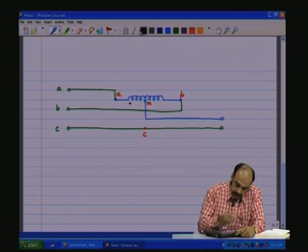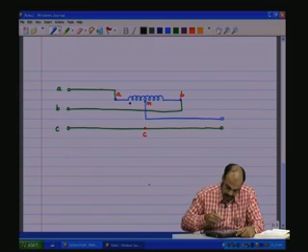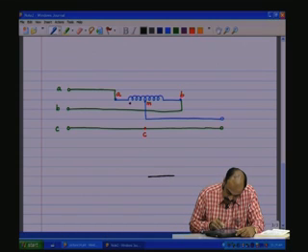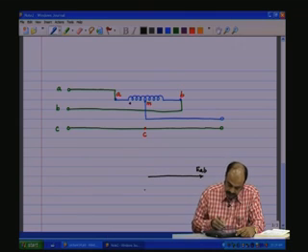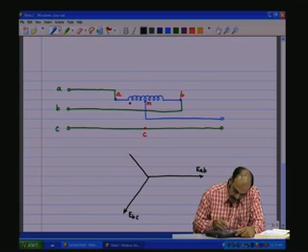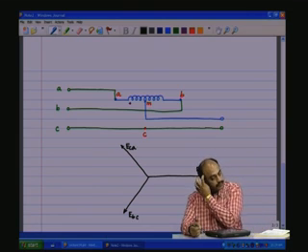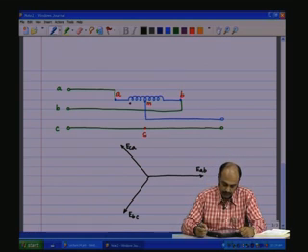Now, let us draw the phasor diagram. Now, we know that ABCs are as follows. If I am having EAB along this, EBC will be 120 degrees lagging EAB, and then you have ECA another 120 degrees lagging EBC, or 240 degrees lagging EAB.